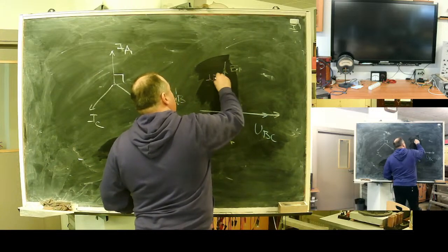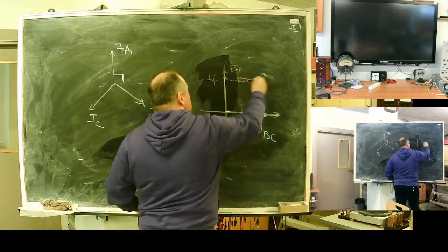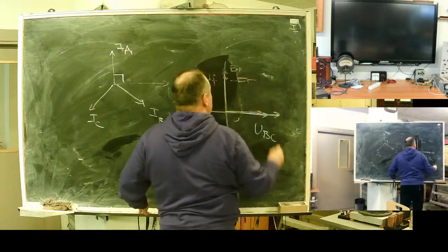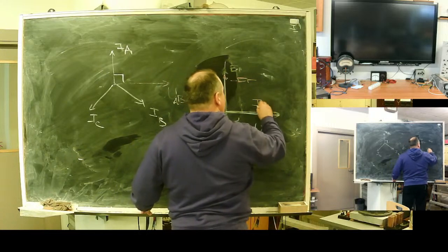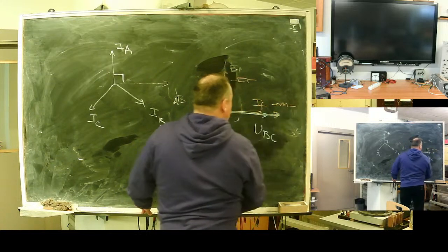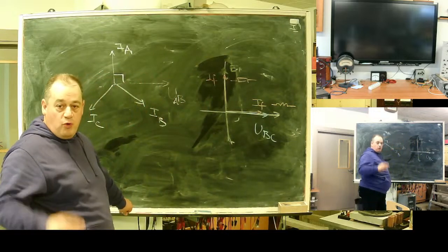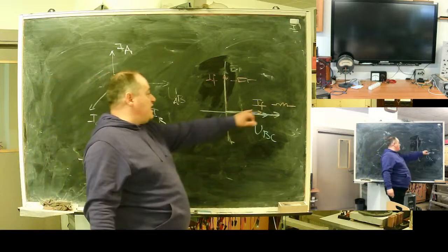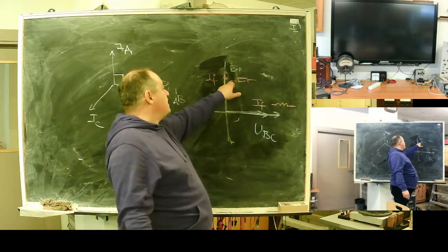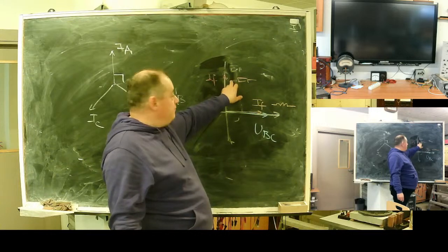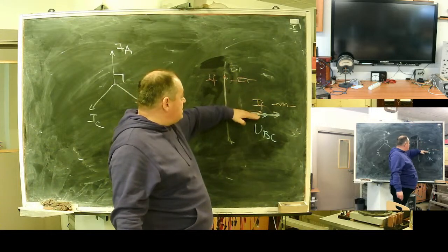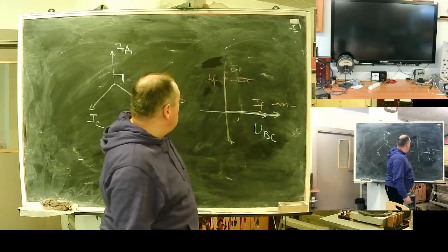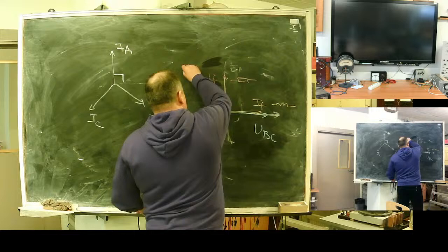This will be a fault in case of pure resistance. Somewhere here will be a fault in case the fault loop is fully inductive. It's a pure inductive case, where R fault is 0, where X fault is 0. So all possible currents will be somewhere here.